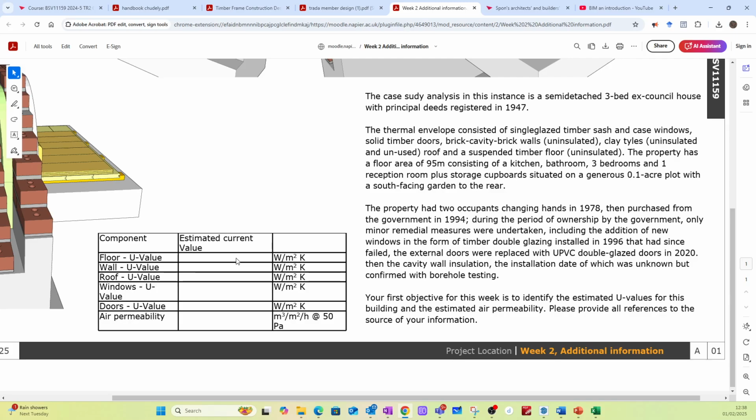We'll be looking at the starting point, analysing that, and for your proposal, you will be suggesting various things. We change the windows to newer windows, or we change the wall insulation, if we do external or internal, or if we even take out the insulation that's currently in the cavity, remove that, and put a more updated material in there, what would that give? And then would you then do further than that? Would you then do additional insulation on the inside or external? And that's a discussion. You give your opinion and you would discuss that with calculations, of course.